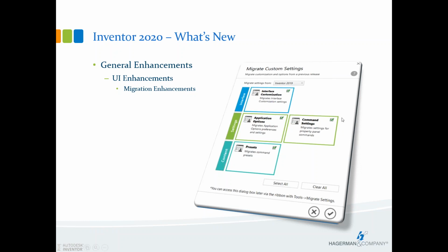The command settings on the right hand side of the box bring in the advanced settings options in the whole panel UI. If you'd saved any of your last used holes, those settings are being brought over. So for the extrude command, the revolve, the shell command, the thread command, those last used options will automatically be remembered and brought forward to future releases as well.